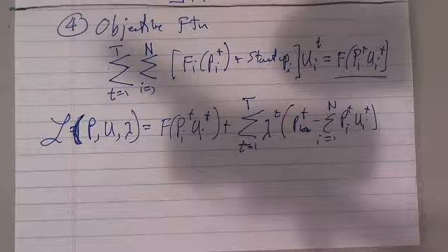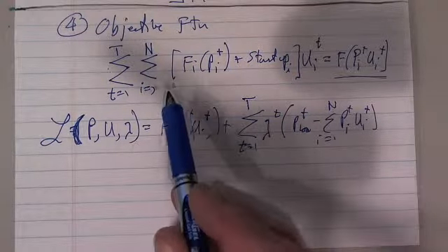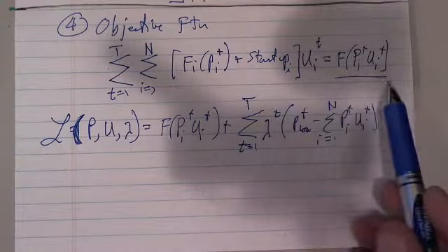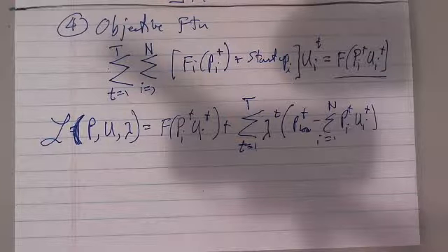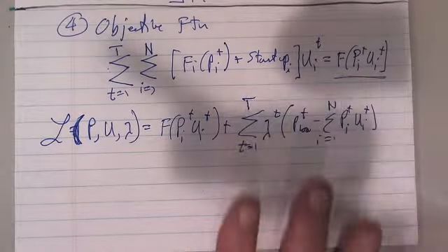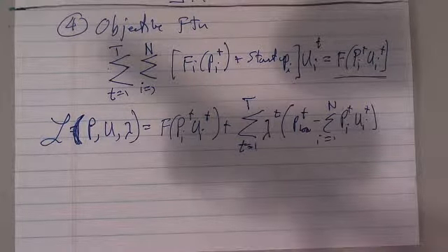But we're trying to minimize the cost that's added up over many hours, and so if I dispatch during the first hour, that might affect how I dispatch the second hour, and so on and so on. You can't simply come along and say, well, for each hour I'm going to do an economic dispatch. I could say, well, for economic dispatch, I ignore that time variable.